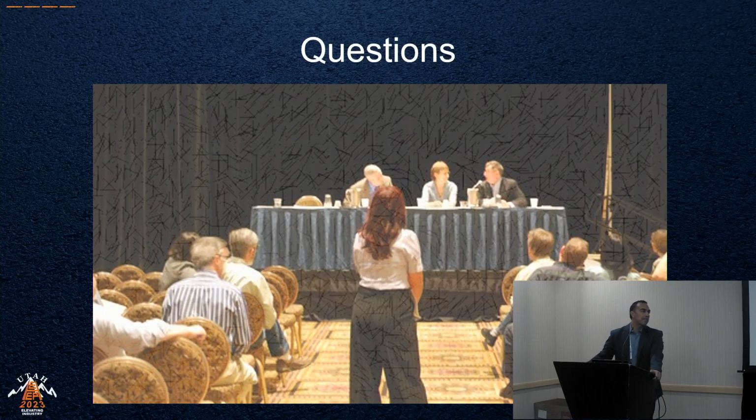Well, an as-built at its core is level D information. The day after it's submitted, it's level D information. So I think that's how designers have to think moving forward on that next project 10 years down the line. We have an idea that a utility's here, so let's go pothole it, or do our one call, and make sure that it's still there. We still have to do that quality check. And I think those potholes will reduce as we start getting a full environment of our utilities that have been shot in. I think there will be less. It's more of a check than it is actually for location purposes.